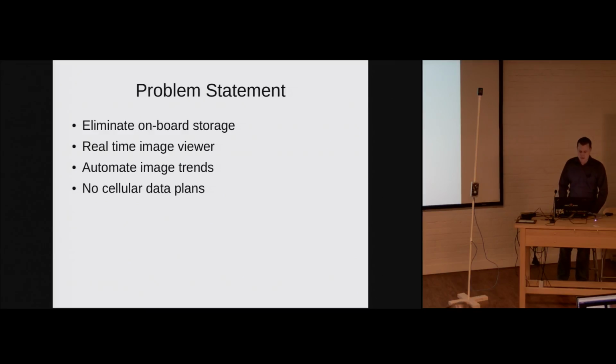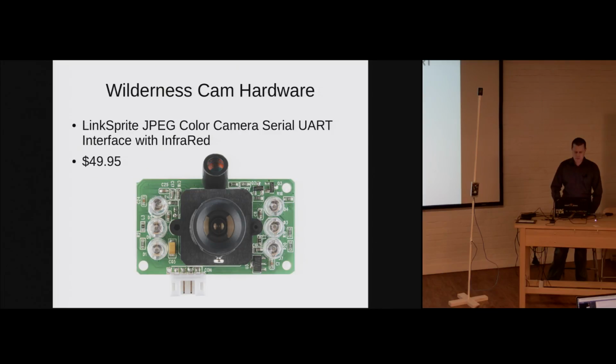And right now, a lot of the boards that I've researched, they operate off the cellular plans, the long-range wireless boards. Typically if you're out in a rural area, you're not going to have cellular service, so it becomes problematic, and every camera that you purchase would have to have a cellular data plan, which is something that I didn't want to have to do. I wanted something that was operating off of a local private network, but still had the benefit of transmitting wireless signals long range that you wouldn't get from your typical Wi-Fi network.